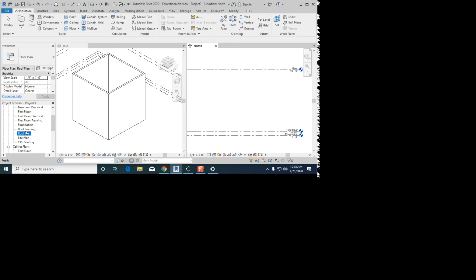Yeah? So that's the other thing about BIM modeling. When you see an elevation marker that indicates a level, that level is tied to a floor plan. So if you delete the elevation marker, the plan is gone. And if you delete the plan, the elevation marker is gone. So again, it's kind of doing all of the annotative drafting for you so you don't have to think about it. Okay, so now our second floor is gone because we don't have a second floor. We just have our first floor, and then we essentially have where the roof and the ceiling is.